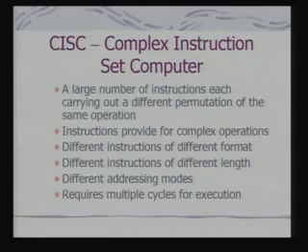So, we find that the basic philosophy which goes into the CISC design is more complex operations being implemented in hardware, and a more elaborate way of accessing data as part of the instruction set, because of the addressing modes. Addressing modes give you a variety of ways of accessing data in the memory, and you can even have operations involving data in the memory. These are the typical characteristics of a CISC processor.